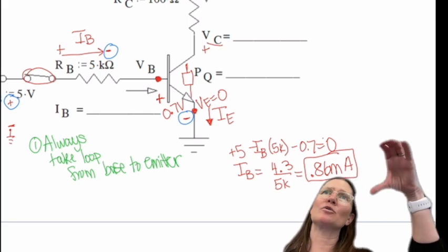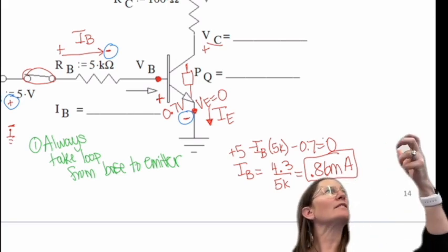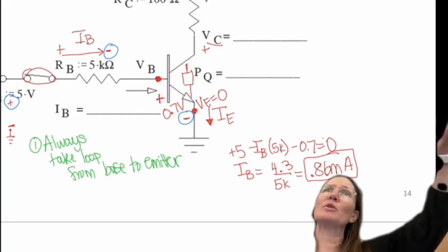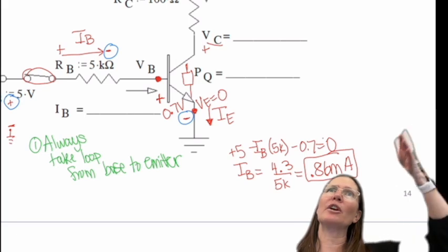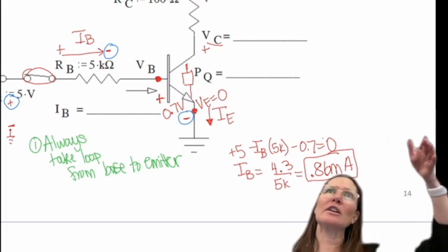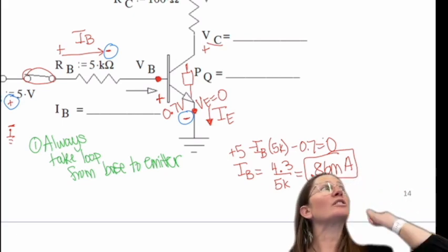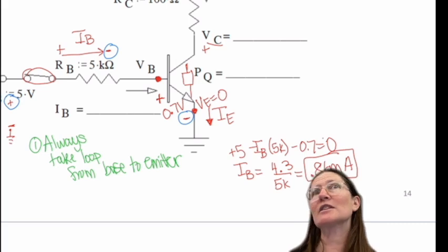It doesn't act like a normal diode. So we can't say it's easily just 0.7 volts across there. It's actually only like 0.2 or 0.3 when it's fully saturated, but it varies internally based on how much current is coming in. So it's an unknown value between VCE.